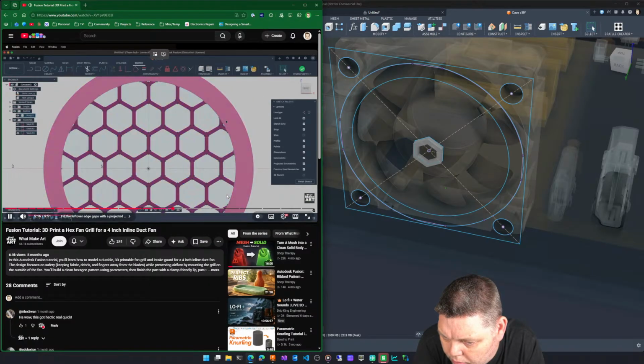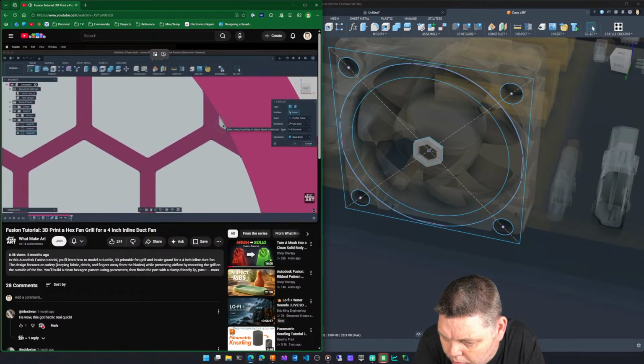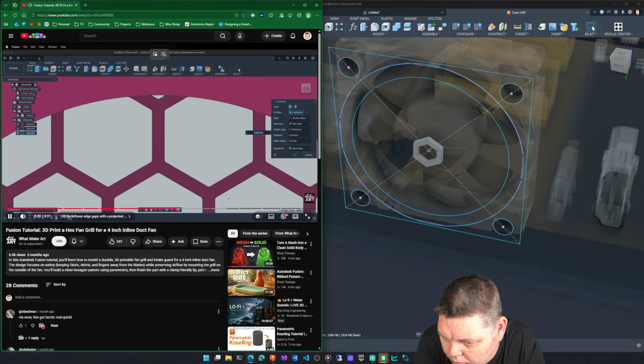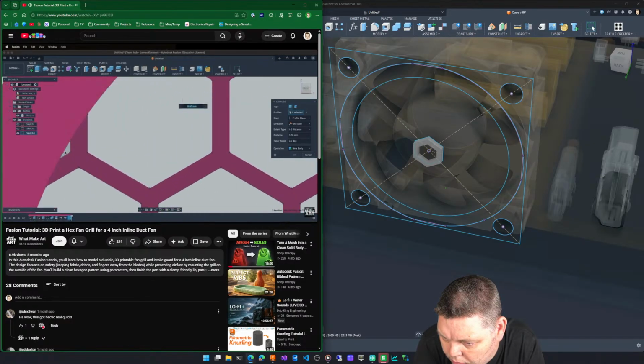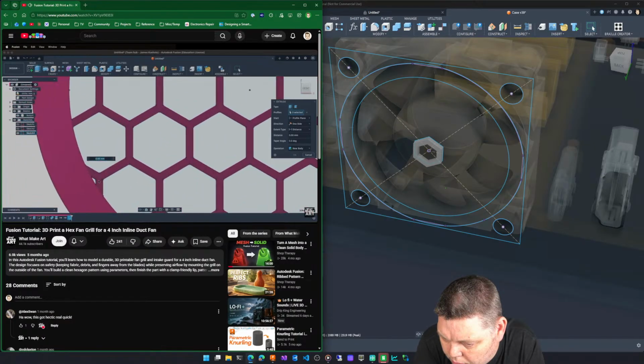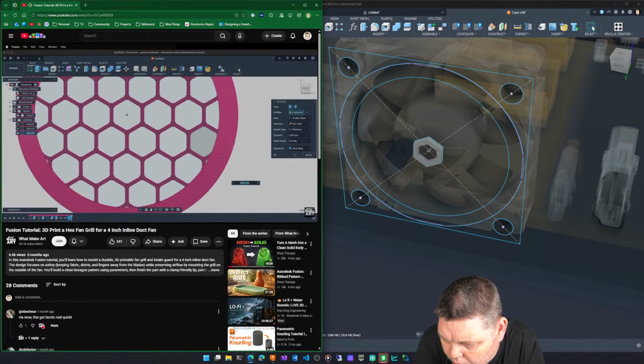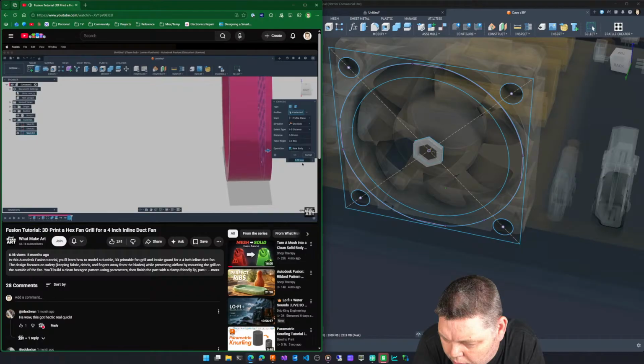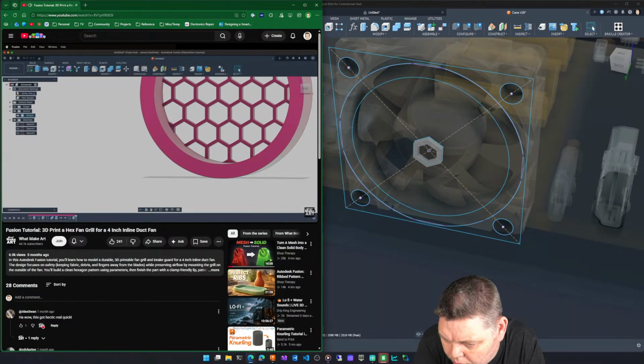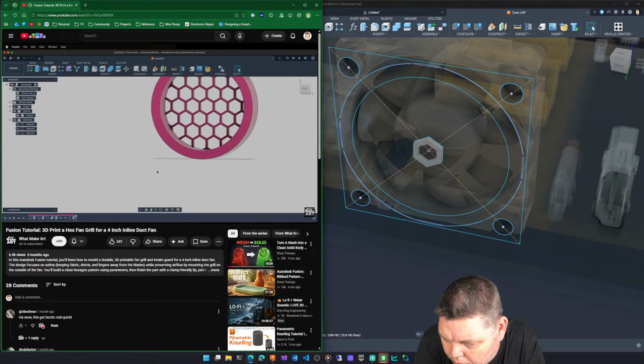And I'll say OK. Then I can just press E and select all these profiles right here. This does add a lot of extra geometry to the sketch, but for the most part, it's not that heavy, and it's faster than going around and clicking each individual line. And if I look here, I want to extrude this way, so the distance will be 5 millimeters. Make sure the operation is joined and press OK. That fills in all these little gaps, so it makes chamfering easier.